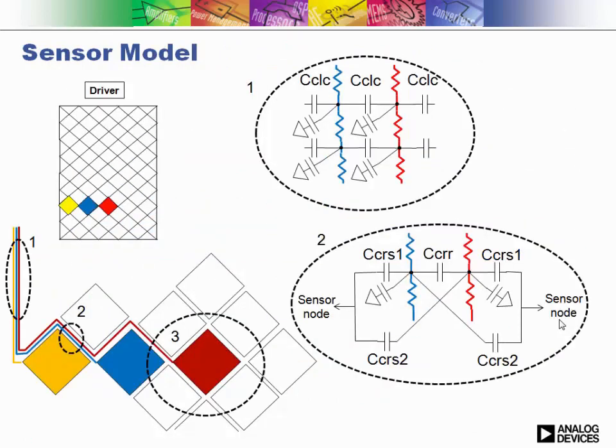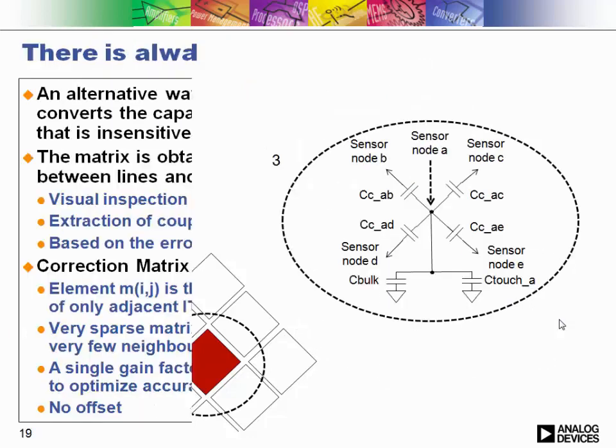Just to let you know what kind of model we had for simulation to reproduce the system and also reproduce the error: we took this whole sensor, replaced it with just caps between routing and sensors, and put up a full mesh of caps and resistance. Okay.